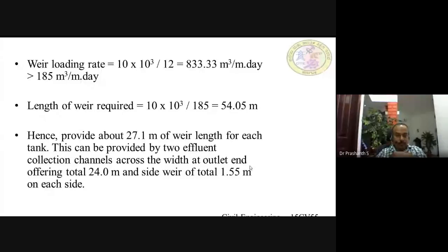Definitely you go through the textbooks and try to solve more number of problems. This is how the sedimentation tank is designed. You can design the circular tank also. So the main assumptions that we generally make are surface loading rate, then width, then the detention time. These are the things you have to keep in mind while designing the sedimentation tank.